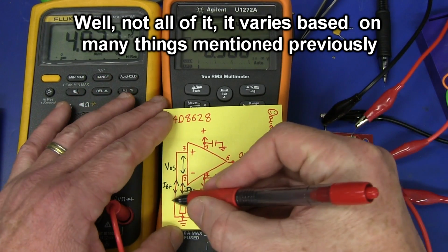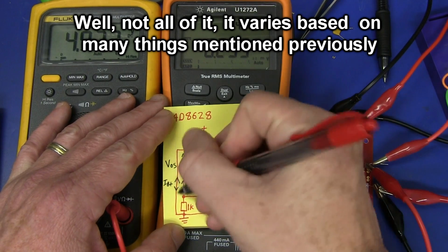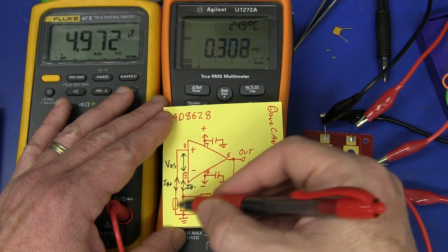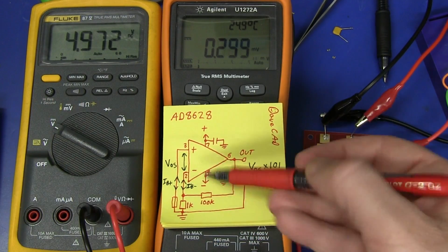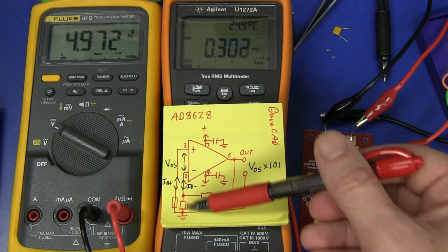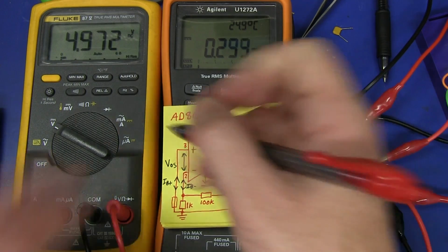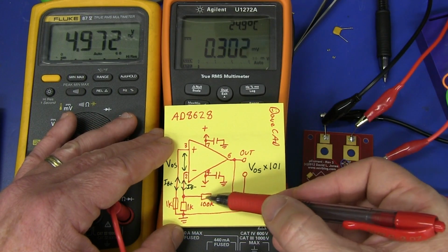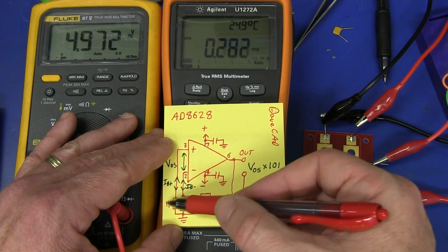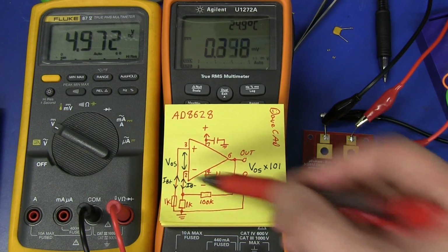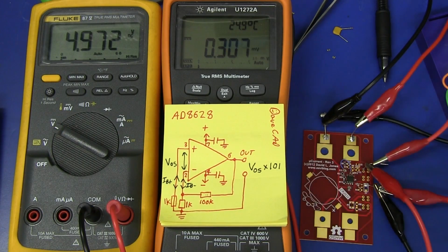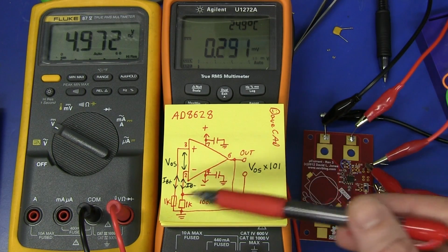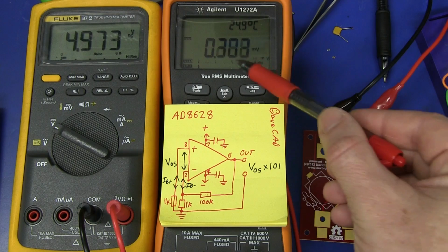That's why I knew that I could have put an additional bias resistor in here like this, but then I sort of did the math in my head as I was going along, and I went, oh, it couldn't make an effect. I could make that one 1k, of course, as we talked about. It should be 100k in parallel with 1k, but it's going to be pretty close to 1k. So we can put that in there, but I think we'll find if we do that, and we will do it in a second, that this value will actually change.